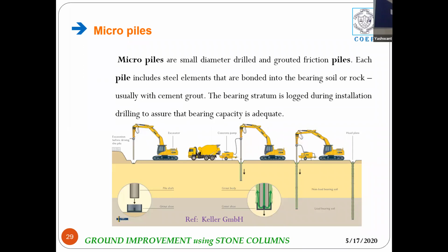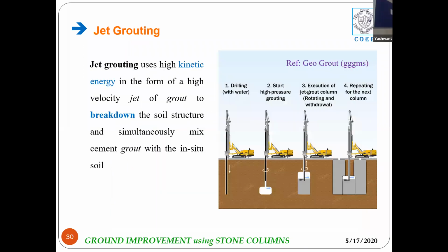Then the jet grouting. Here under high pressure, the grouts are injected into the soil below, thereby breaking the soil structure and simultaneously mixing cement grout with the parent soil there.